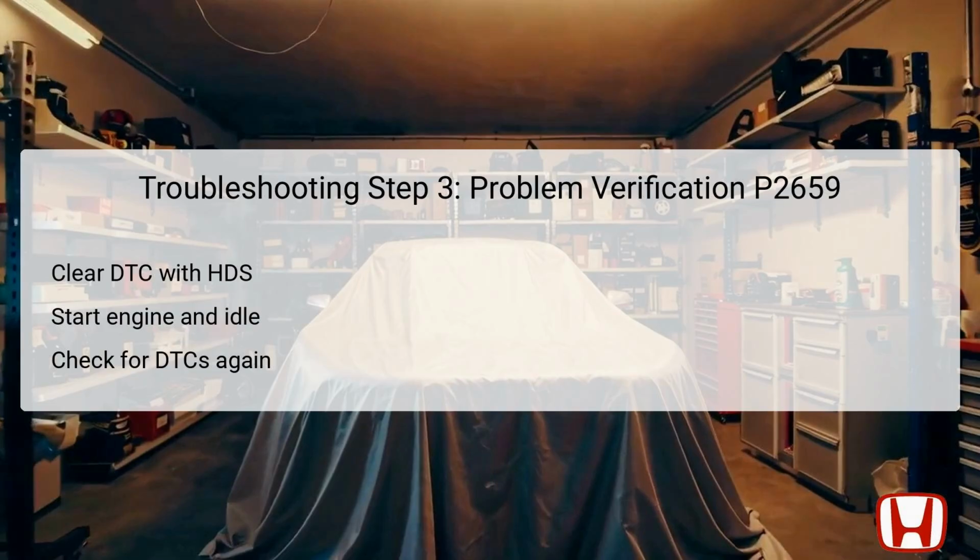After addressing the fuse check, the next step is to verify the problem by clearing the DTC using the HDS. The vehicle should be turned back to the on mode, and the technician will clear the existing DTCs from the system. Once cleared, starting the engine is necessary to observe its behavior. The engine needs to be held at an elevated speed, specifically at 3,000 RPM without load, until the radiator fan is activated, followed by allowing the engine to idle.